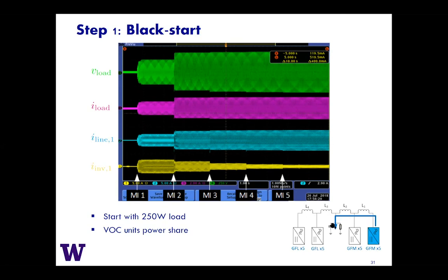But what makes this challenging is whenever the system is de-energized, it's not as if these inverters have switches that are separating them. They're all connected to the system. It's just that their power electronics, all the semiconductors, are acting like open switches. Now that means that although the switch part of the power stage is open circuited, the filter elements are there. So each one of these inverters has inductors and capacitors hanging out on their outputs just on the system. So when you're this lonesome inverter that has to turn on first and you're looking out, you see a bunch of inductive lines, a capacitor here, and a bunch of L's and C's on all the filters,